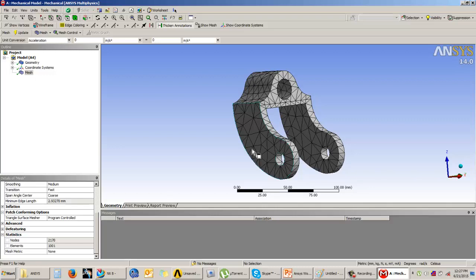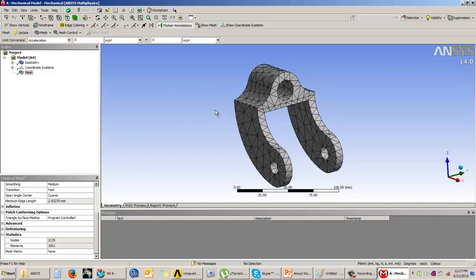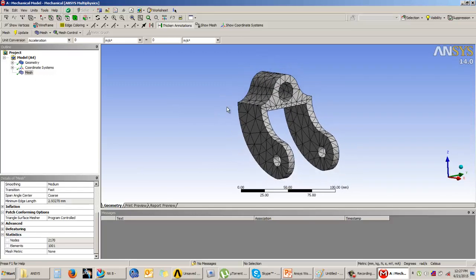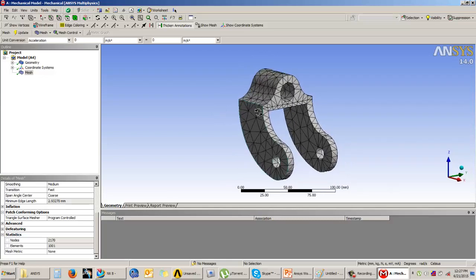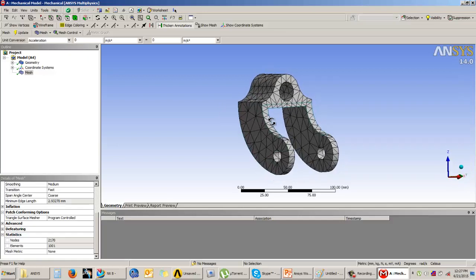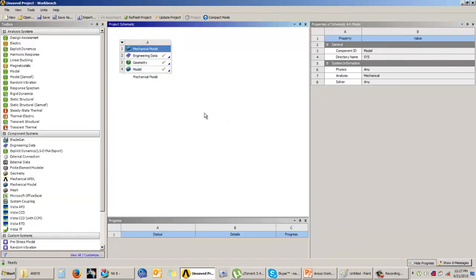So that is why, whenever you start meshing, the first aim that you should have is to generate hexahedral elements. Wherever it is possible, you should always generate hexahedral elements. Now in this case of our geometry, we have seen that we have not achieved the hexahedral elements because the geometry is slightly complex. So if I want to achieve the hexahedral elements, I need to optimize my geometry, or I need to edit my geometry in some cases. So let us understand how to optimize this geometry.